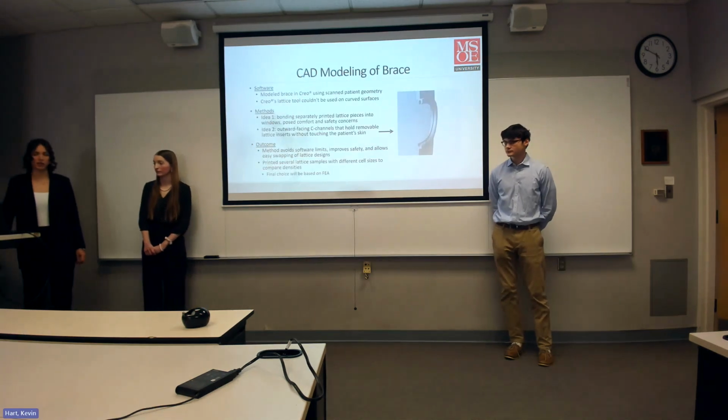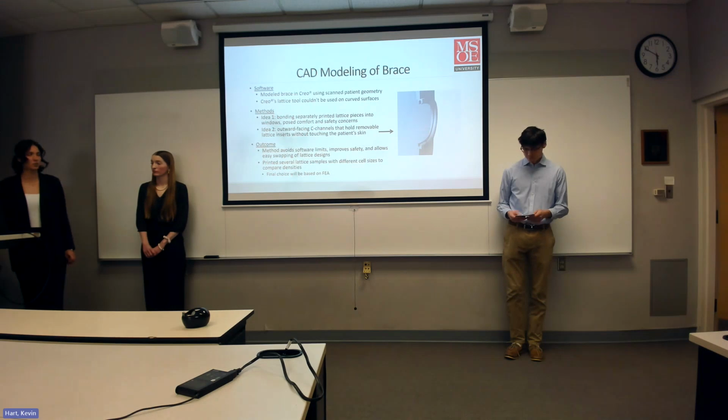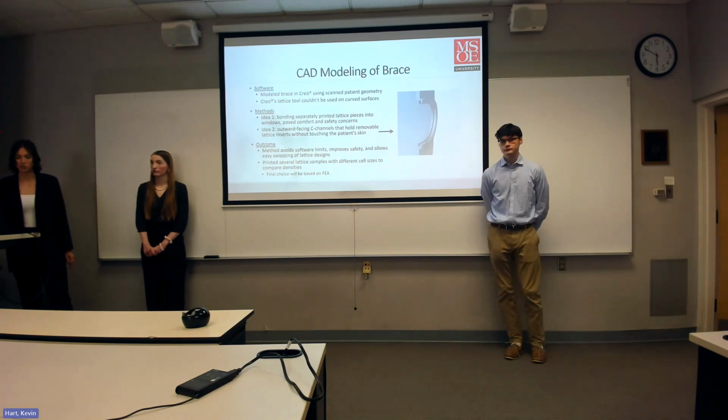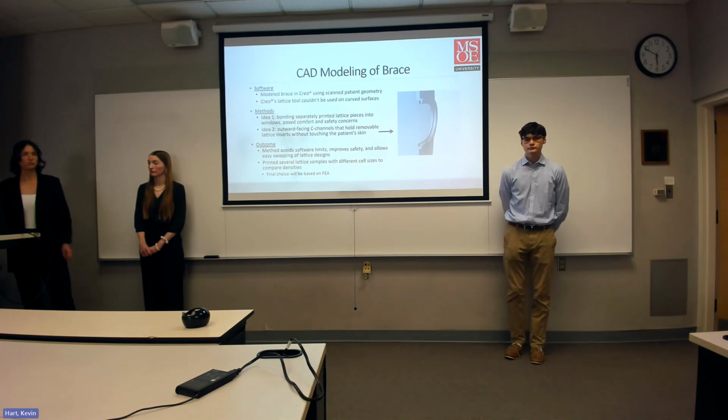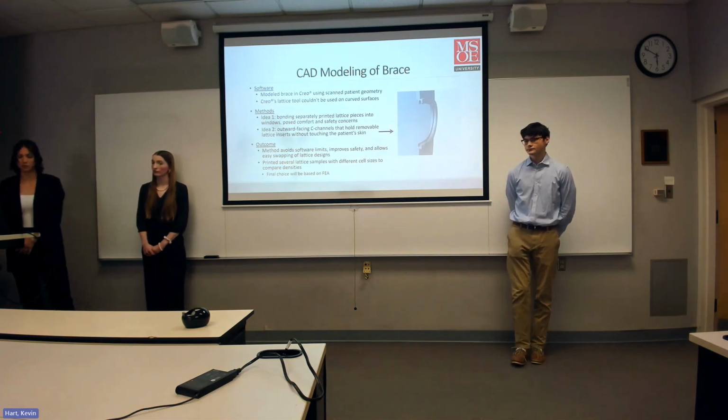Next, into the CAD modeling of the brace, it was primarily done in Creo, and we quickly found out that Creo's lattice tool could not be used on curved surfaces. It would only work on planar surfaces. So this led to a couple of ideas of separating the lattice from the brace basically.